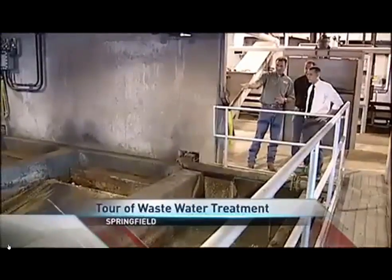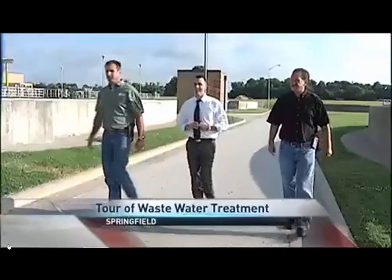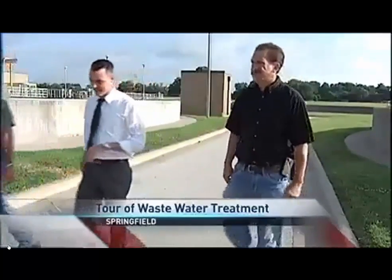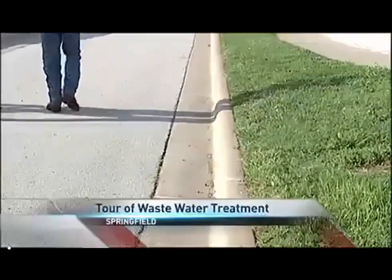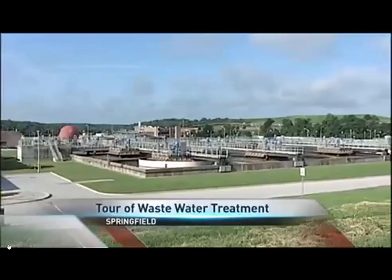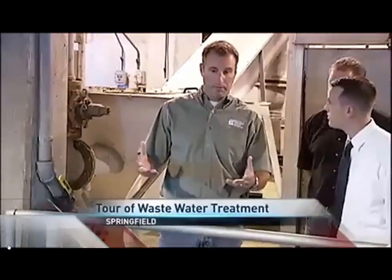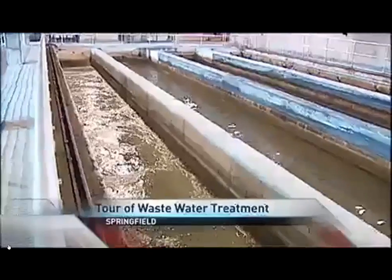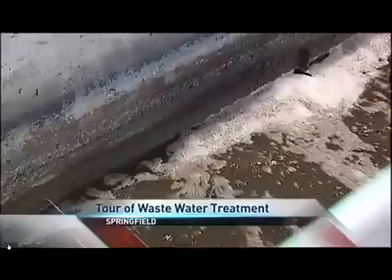Kelly Green is the plant manager. We average about 28 million gallons a day right now. He walked us through the 60-acre facility, which is manned 24 hours a day, 365 days a year. Water that goes through 4 stages and can spend 24 to 12 hours within the system. This is our headworks facility. This is where the wastewater first comes into our treatment plant. We're going to screen out any of the rags, grit, grease.